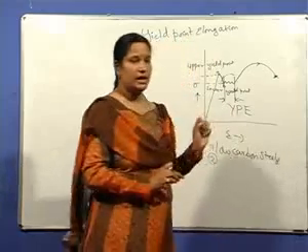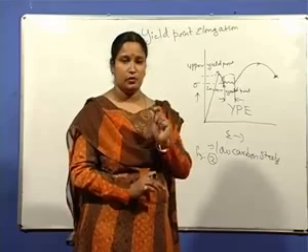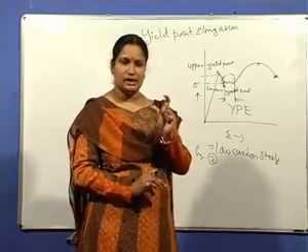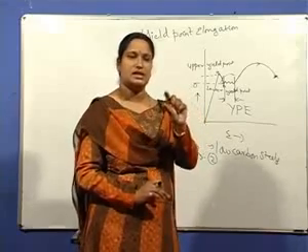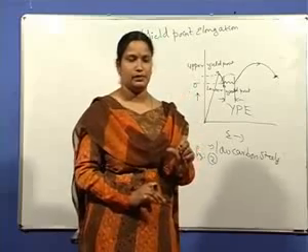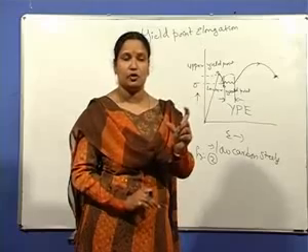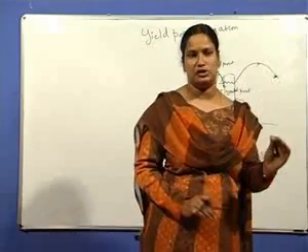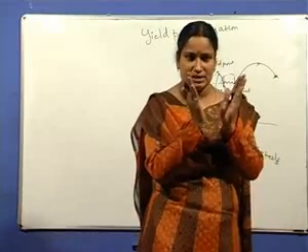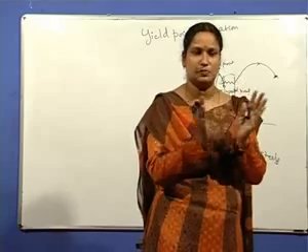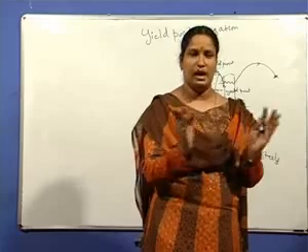Now I'll draw the diagram for the case of substitutional solid solutions, where the solute atom is slightly bigger or slightly smaller than the solvent. Where it occupies was discussed. If it is slightly larger, it occupies the locations below the edge, where the lattice expands. If slightly smaller, above the edge dislocation, where the lattice contracts.